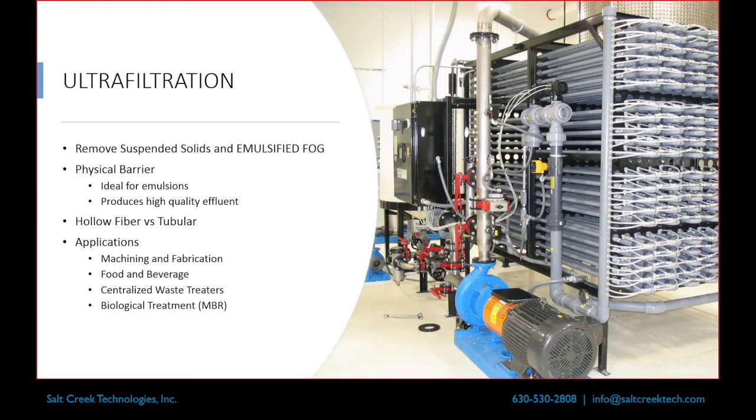They are a physical barrier, so you're pushing the water through a hole that's 0.02 micron in size. So any oil is going to be retained and any solids are going to be retained for the most part. Soluble portions of the wastewater are not going to be retained though. So that's important. You're not going to get soluble BOD reduction. You're not going to get metals reduction unless you've already precipitated out those metals.